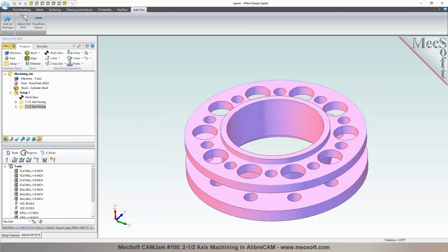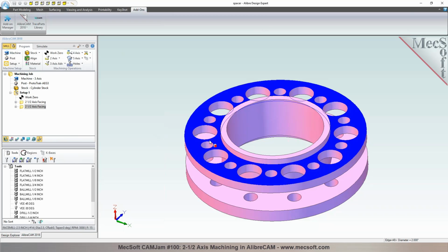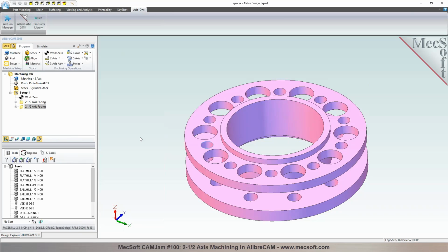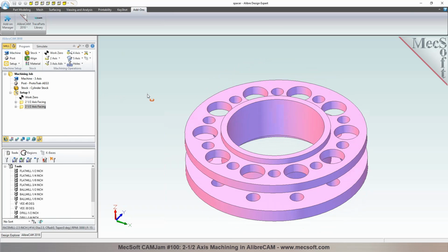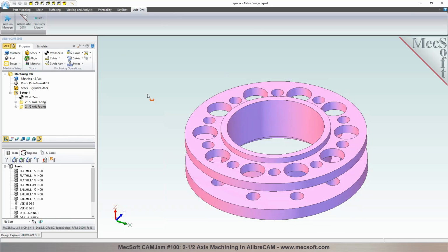Now to program these holes in here, right, you have holes of different sizes in here, right? So this one is a 2-inch diameter hole, and then you have a hole that's a 1-inch diameter. So what size cutter would you like to use for programming these? Well, we'd probably drill the 1-inch holes, and then, I don't know. Generally, I would drill a 1-inch hole in the big ones and then interpolate the rest of it with a, I don't know, maybe a 1-inch cutter.